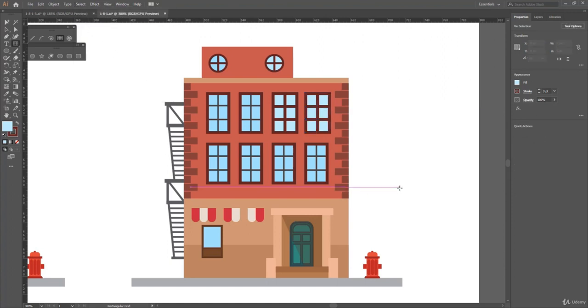Now I'm going to make the dividers for the windows I have created thinner. To do that, I come over to the tools panel to the left, and I click on the direct selection tool to select it, and I come over to this window. So with the shift key pressed, I select the horizontal and vertical lines. I release the shift key, and I come over to the properties panel, and I decrease the stroke width. Now I'll do the same to the other window.